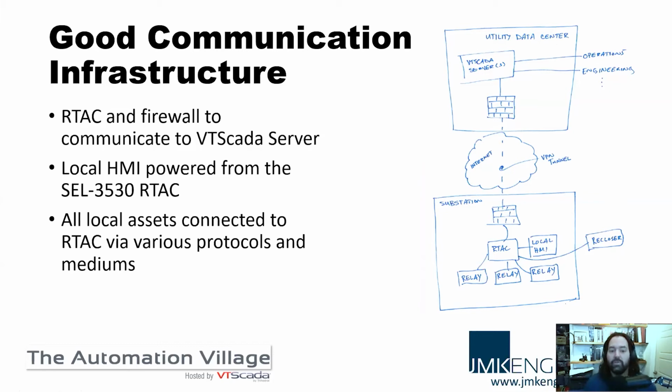Because the IT group's gone through and decided what the various groups and entities need within the organization, they can create all of the widgets that need to be built and create their standard tables in their VT SCADA application. That means every substation, every generator will have similar I/O, similar points, but some of them might be blank. This reduces the amount of development time per site drastically. It takes a lot of time to get it done the first time, but after that, you're done. For Nova Scotia, for example, there's 34 generating stations for small hydro. So if you take a little bit of time to do the first one, you can do the rest of them really quickly.